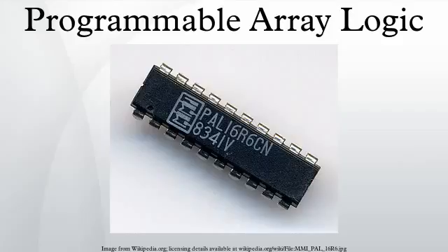Device programmers. Popular device programmers included Data I/O Corporation's Model 60A Logic Programmer and Model 2900. One of the very first PAL programmers was the Structured Design SD20. They had the PALASM software built in and only required a CRT terminal to enter the equations and view the fuse plots. After fusing, the outputs of the PAL could be verified if test vectors were entered in the source file.